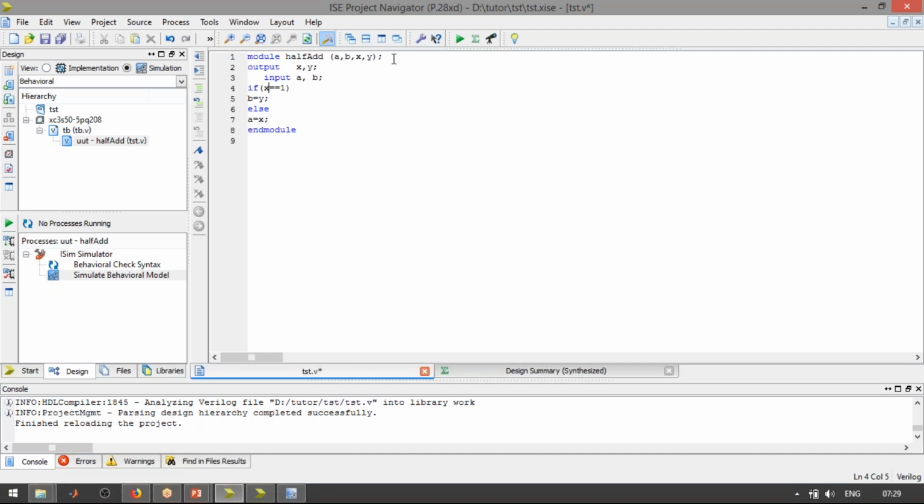So in that case, if I'm using the always at statement, here we are not declaring any clock pulses. So my behavior entirely depends on the inputs A and B. Whenever the input changes, the output will also change. So actually, if I am giving the input, then it is level triggered. Based on the levels of A and B, it will automatically change the output. In the case of a clock, if you want to use the positive or negative pulses, that's the difference between those declarations.